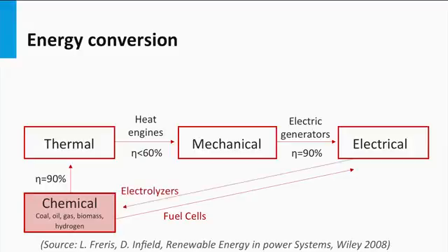A regenerative fuel cell operates in reverse mode and converts electrical energy into chemical energy. Such an operation is called electrolysis, and the device operated in such a mode is called an electrolyzer. Typical conversion efficiencies of hydrogen electrolyzers of 50–80% have been reported.